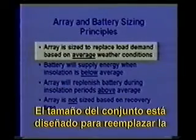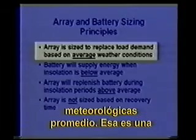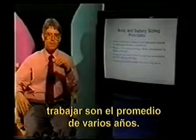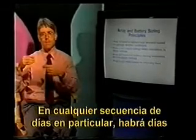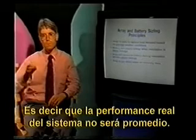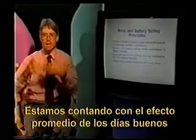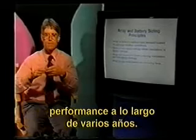The array is sized to replace the load demand. It's based on average weather conditions, though. That's a real important consideration. The weather data that we have to work with is averaged over many years. In any particular sequence of days, you'll have above average days and below average days. So the actual performance of our system will not be average. We're counting on the averaging effect of good days complementing bad days to give us good performance over many years.